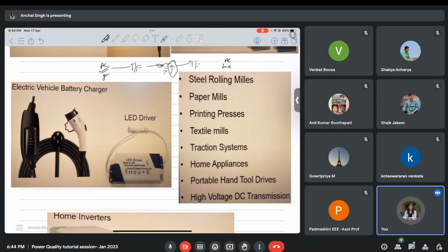On the contrary, if you have to transfer the same amount of electrical power over longer distances, what you could do is use an AC to DC converter here, and then a DC to AC converter here. Since in DC there is no significance of a capacitor or an inductor, all those problems go away.